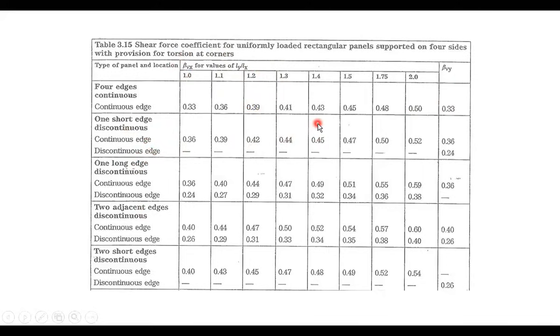Okay. But keep in mind for the shear, if you are designing slabs or a floor with different slabs, you need only to check the shear one time, because you take the critical shear, the value of the maximum shear, and check this value. If the shear is safe, it means at any lower values, the shear also will be safe.